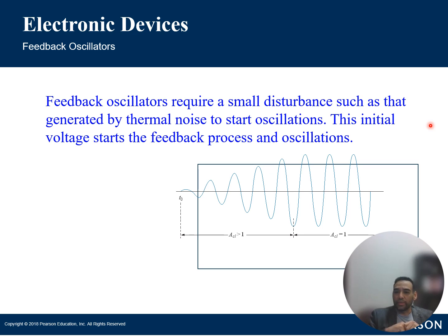All right, so stability analysis. You're going to conduct a stability analysis, and you do this to understand how those small disturbances affect the oscillator's stability margins. So margins is the word I was trying to think of earlier. In this analysis, it can involve techniques like loop gain, phase gain, margin analysis. And what you do is you use this to actually go back and optimize and look at your component selection. So choosing the components with the tight tolerances, low sensitivity to environmental factors, those can actually help minimize the impact of those small disturbances on the oscillator's performance.